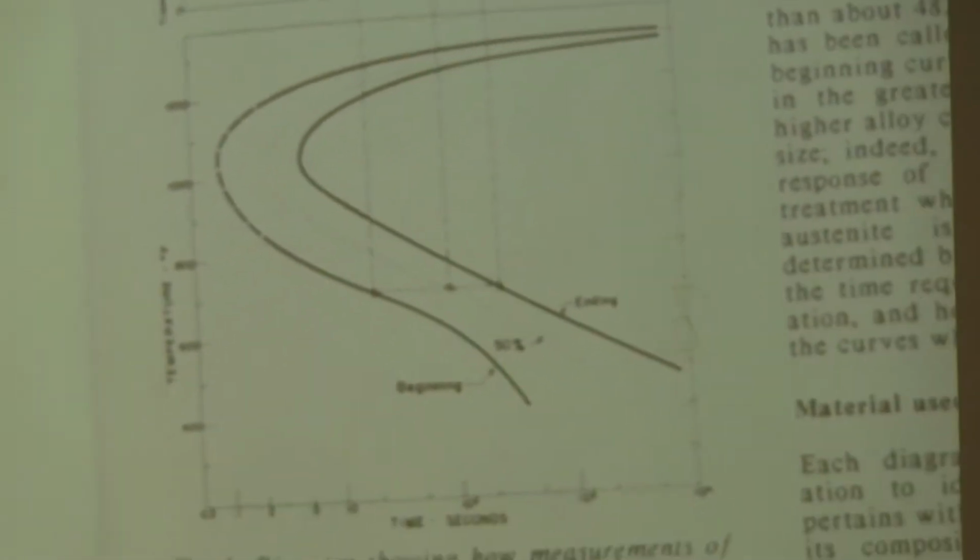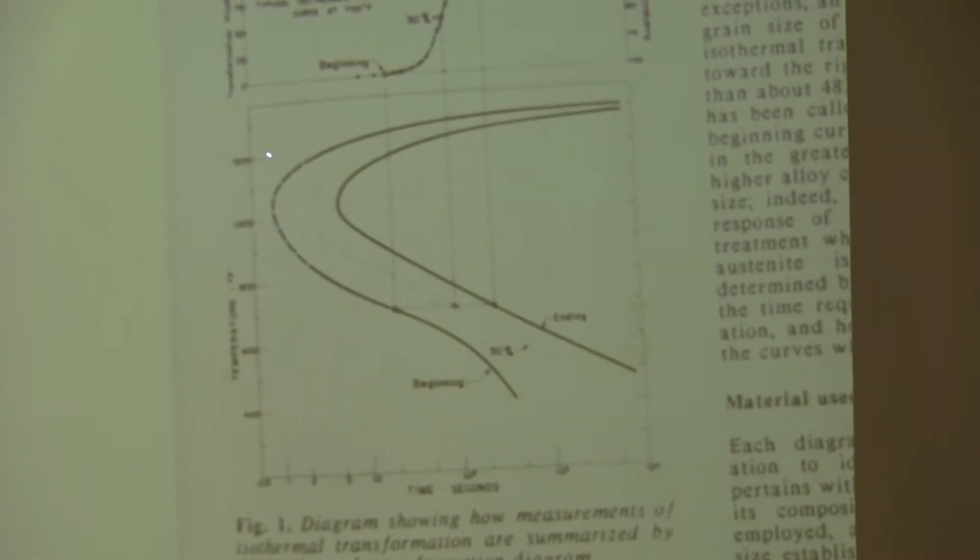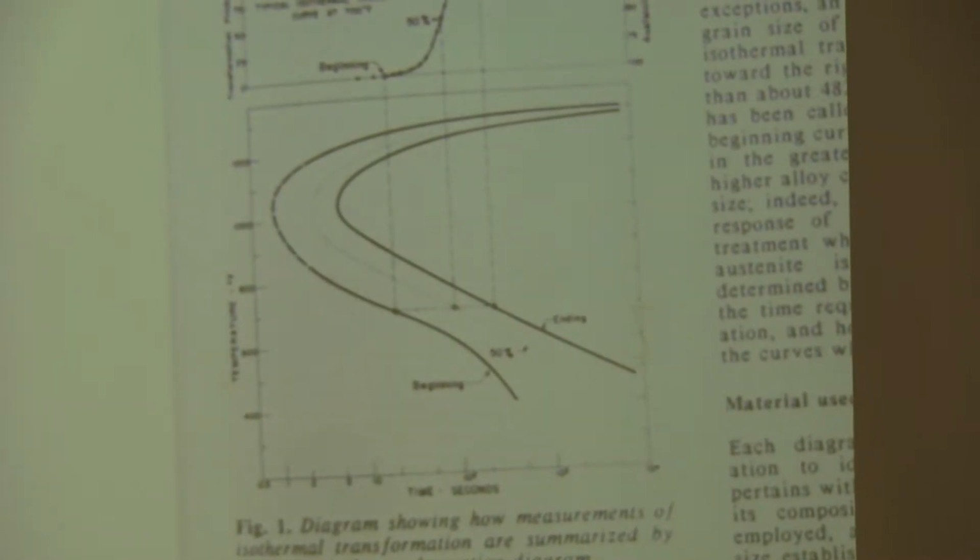I'm going to take it up here above 1200. I can't read it. Fine, 1200, yeah. This is above 1200 Fahrenheit, so I take it up to 1300, 1350 Fahrenheit. It doesn't even tell me the type of steel, but anyway. Okay. Anyway, I start cooling it.